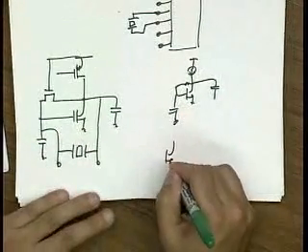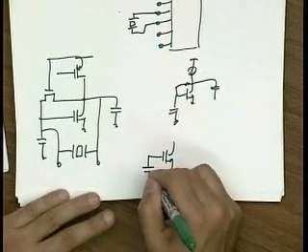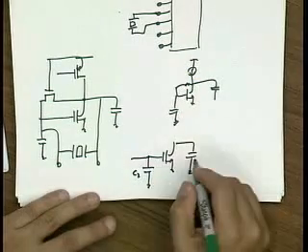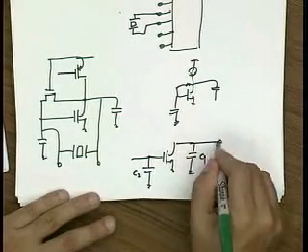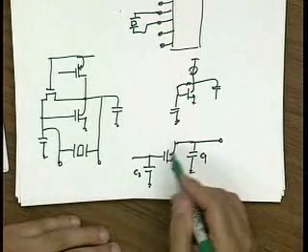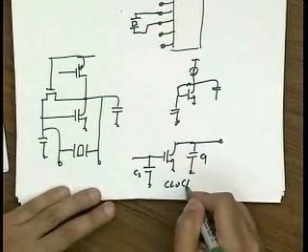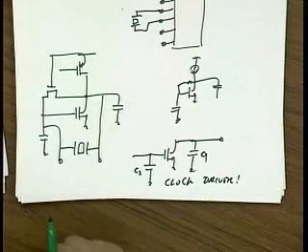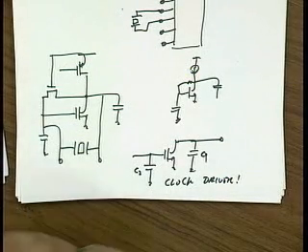Basically the equivalent circuit without the biasing, without the crystal, is just C1, C2. You've already sized this transistor up to be a pretty hefty device, and so it can act as a clock driver. So it's a nice, cute little way of achieving both.